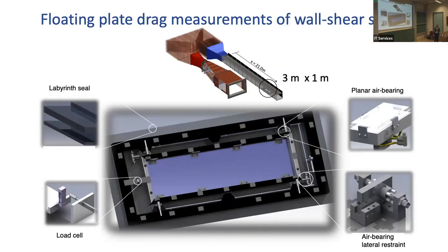And of course, the important thing is that the boundary layer essentially develops very slowly over those 3 meters. Essentially, it's linear. In fact, if I take the centroid and use a Kármán-Schoenherr relation, I'm off by 2 millimeters in 3 meters. So it's a very good approximation. Also, this thing is built to handle very high loads, so it can easily handle anything we put in it without the contamination that you get once you connect things.